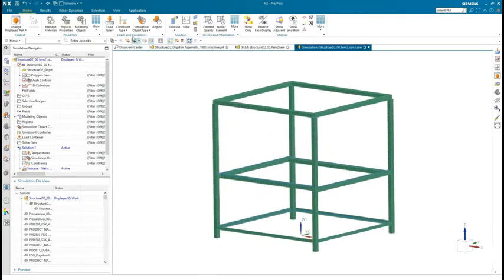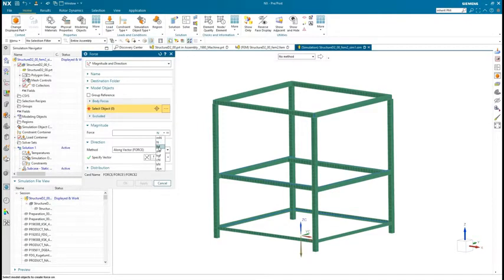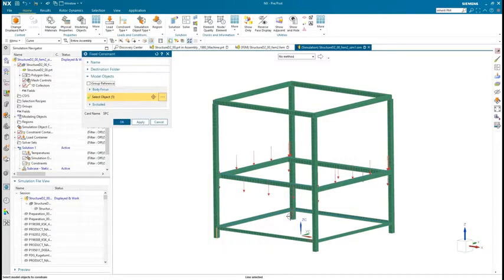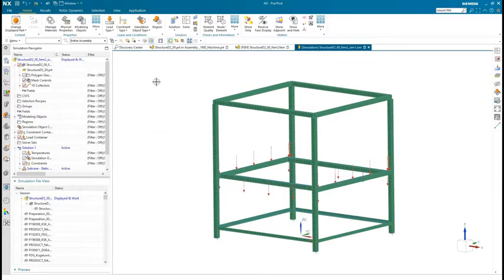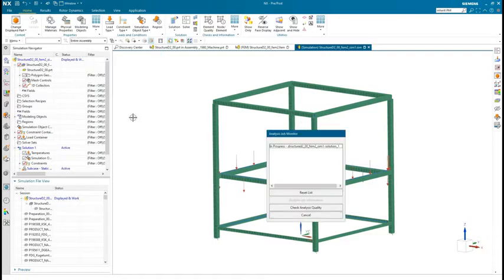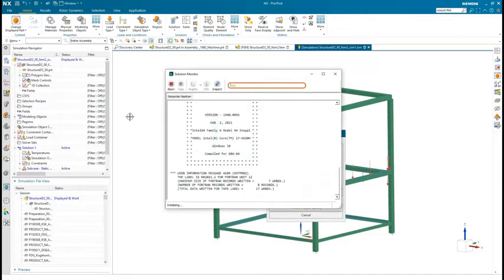As with any FEA simulation, after meshing, it's time to add the boundary conditions. First, we'll apply a constant load to the midsection, simulating the weight of the machine. While 600 pounds is more than the total weight, this will give us a reasonable factor of safety. We'll simplify creation of the fixed restraints and simply select the lower leg sections. Because this model is made from standard stock, beam element meshing and solving will give fast, accurate answers.